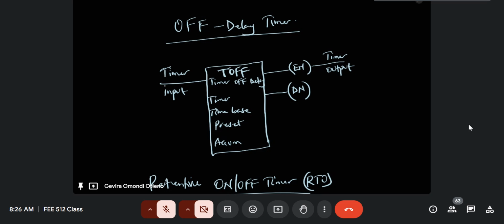You see, in the world we live in, since it's not perfect, every time the power goes off for whatever reason, or every time an off instruction has been provided downstream, that is, if this input is given a logic off or a logic 0, or a logic low, whatever logic it is, or even if there is a power failure, then the amount that was stored here when it was counting down the timer is lost.